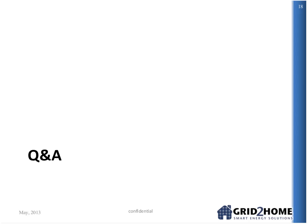Next, Roger Levy. Does ALG support of SEP1 and SEP2 simultaneously require gateway binding to the meter? No, if you're a SEP1 meter, you only need to bind the SEP1 portion of the gateway to the SEP1 meter. The SEP2 portion of it is bound to your HAN devices and, because the gateway resides in the consumer premise, can be under the total control of the consumer. So the answer there is yes and yes, if you've got a SEP1 and a SEP2 meter.